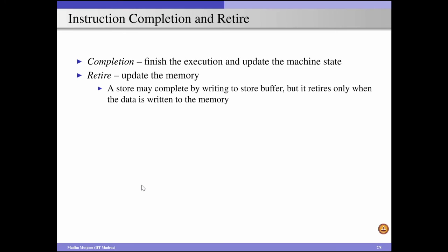So in other words, a store may complete by writing to the store buffer, but it retires only when the data is written to the memory. There may be several cycles between writing to the store buffer and writing to the memory, because the memory may be busy dealing with the load instructions and so on.